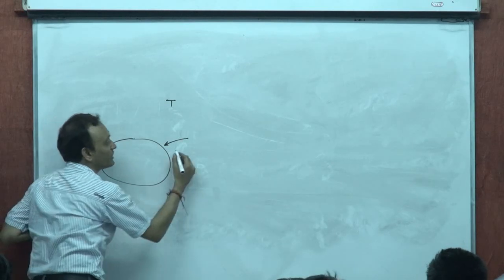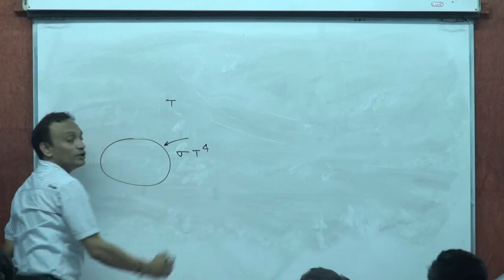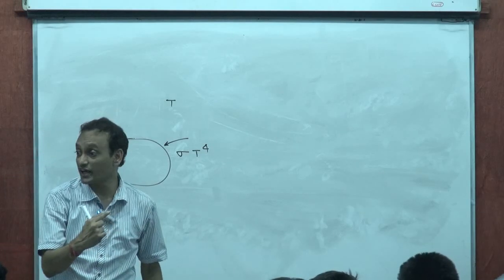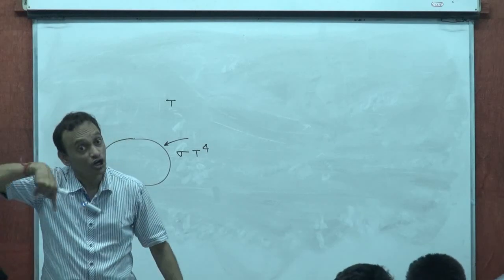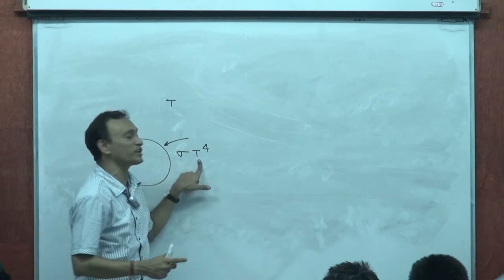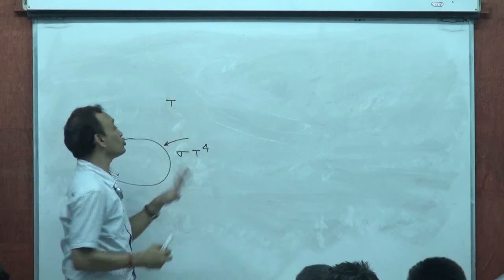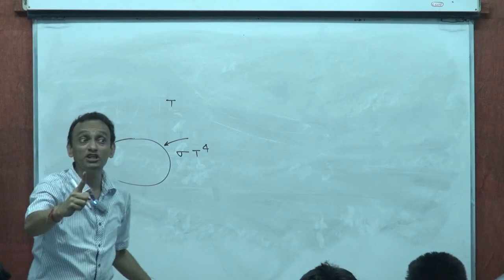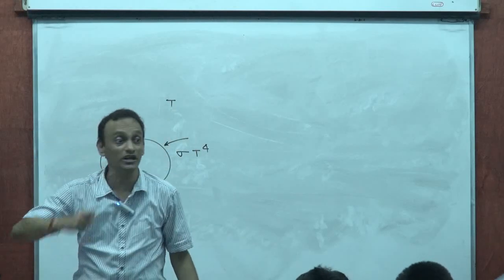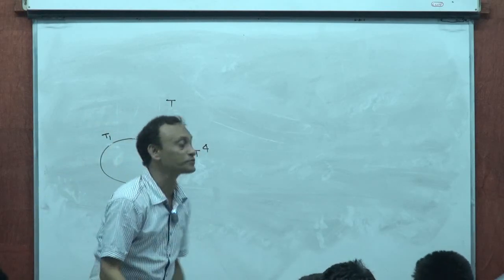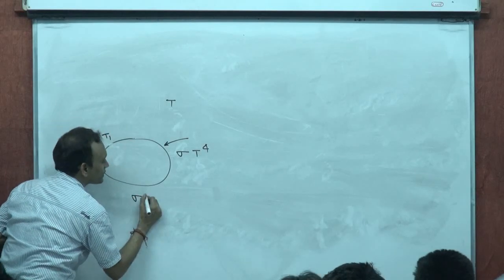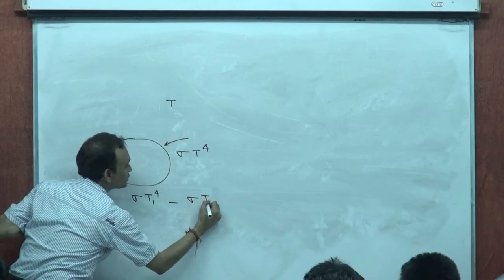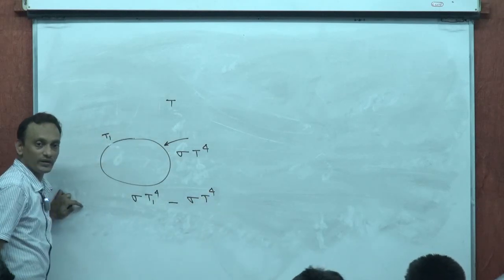It will absorb heat in the form of radiation, which will also be of the form sigma T to power 4. So this is not only the emission characteristics, the sigma T to power 4 is also the absorption characteristics. Absorption also takes place commensurate with sigma T to power 4. So, if there is a body, let's say a perfectly black body, at temperature T1, then there would be simultaneous emission as well as absorption. The emission here would be sigma T1 to power 4 watts per meter squared. The absorption here is going to be sigma T to power 4 watts per meter squared.